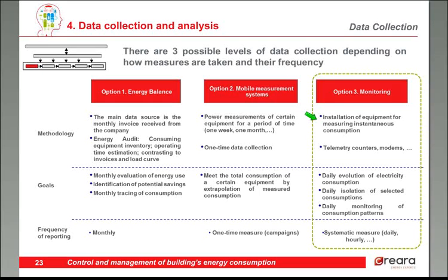The second option is creating or building campaigns with mobile systems to have a check and to monitor energy consumption in a building. I mean, this equipment is typically installed for a period of time, for example, 1 week or 1 month, and then some conclusions are drawn from this, let's say, short analysis.